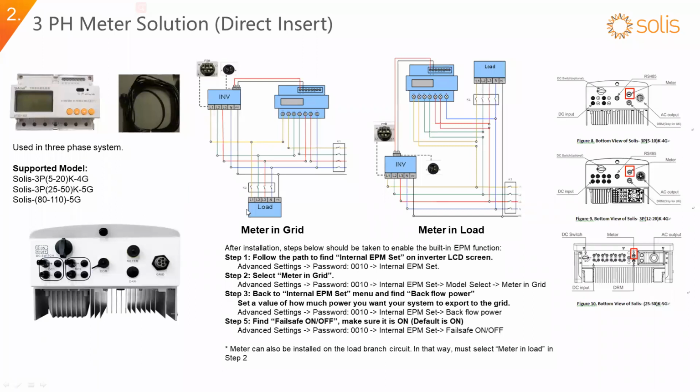What distance should be maintained between RS-485 and the power line? A wireless connection is not possible. 10 centimeters is the standard we can follow. 10 centimeters between the power line and communication is the standard followed in the industry. Thanks.